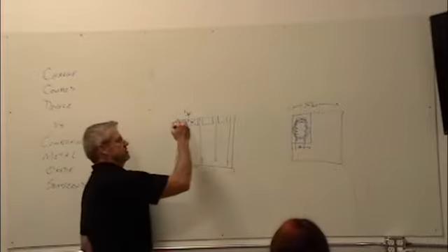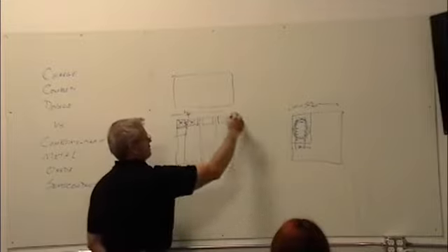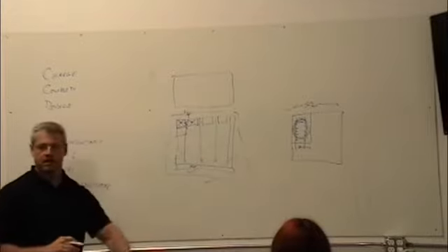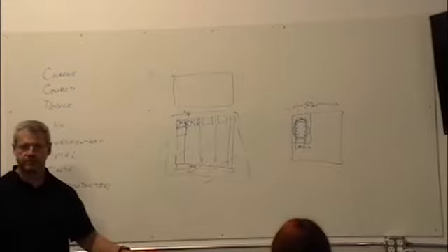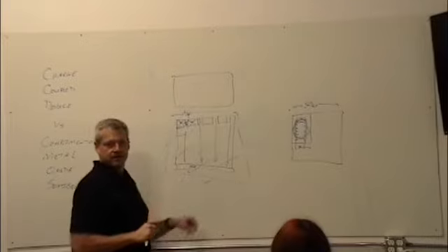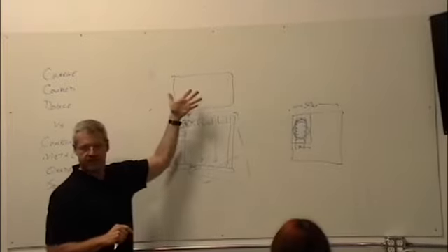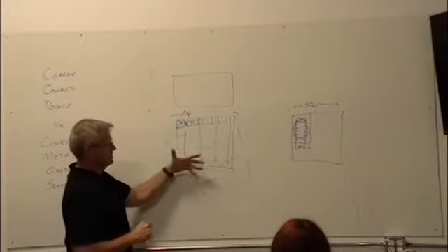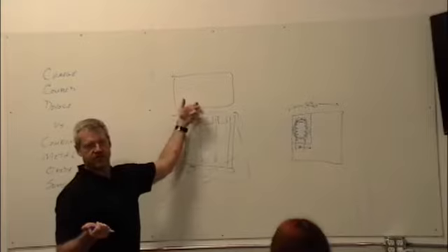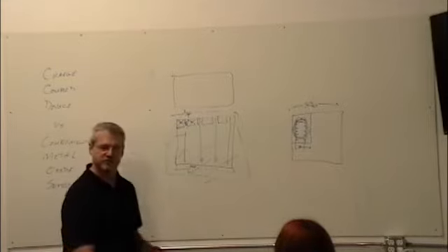One of the other games they do is they'll take a register here, they'll have the CCD here, and this will be all metal over, so no light will hit it. And they'll take this and shift it out really fast there, and then go back and do the imaging on this one, because when you shift it out, you clear it, right? It empties it out. So they'll empty it all into this one, and then they can sit here and leisurely read this one out, while this one's still integrating. So it's not quite exactly frame to frame to frame, but it's pretty close.